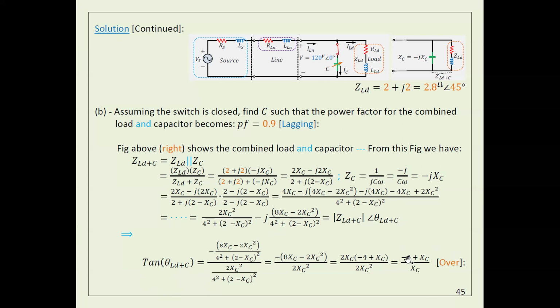So what I want to do right now, guys, is see: I have C here unknown. C is unknown, but I can find tan of the angle. Why? Because I already know the power factor is cosine of the angle. You have the cosine of the angle, you can calculate the angle, and then you calculate tan, because this angle is actually theta V minus theta I.